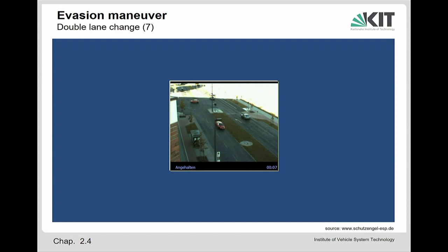But you can see that the rear axle is overloaded. You see that here from this step to this step. It's not just driving forward. Also the rear is sliding. It starts to slide. So it was already too much what was requested from the rear axle. And now, because of this sliding, the rear of the car is coming onto this grass area.